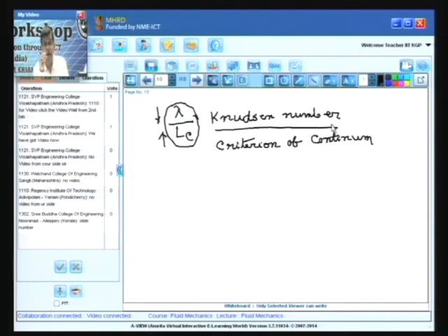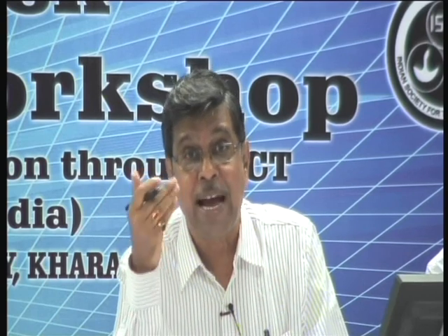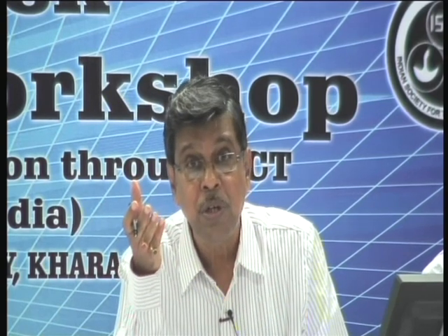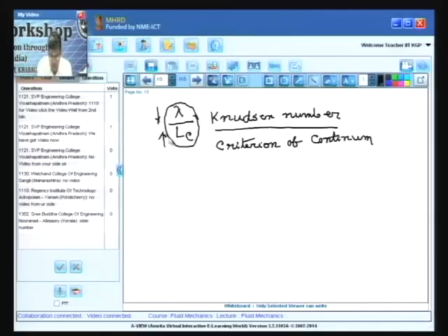So, there also the probability of the number of molecules residing will be higher. So, uncertainty in the measurement of the property as the manifestation of the gross average behavior of the molecules will be reduced. Therefore, we see this ratio uniquely determines that. That means a lower Knudsen number, that means a lower mean free path or a higher characteristic length of the system, is favorable for accuracy of the measurement of the macroscopic property as a gross behavior of the molecular behavior. That means the continuum approach will be much more valid, while the reverse is also true.